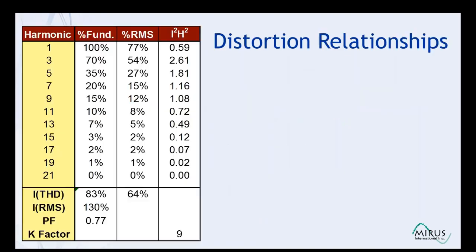This table on this slide shows a typical harmonic current spectrum for a single phase to neutral nonlinear load. It could be a switch mode power supply that you might find in computer equipment or LED lighting or a similar type power electronic load that has not been power factor corrected.